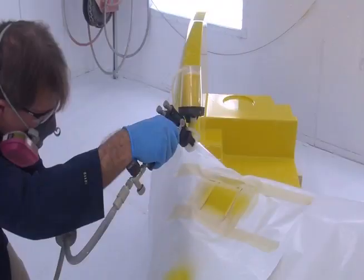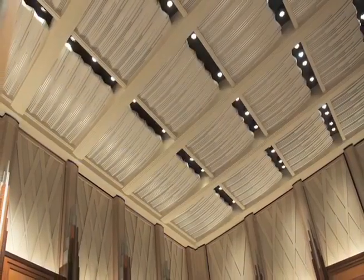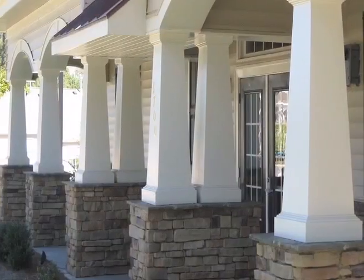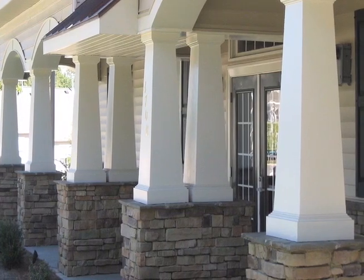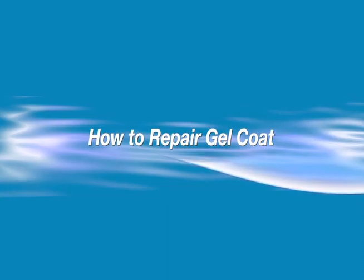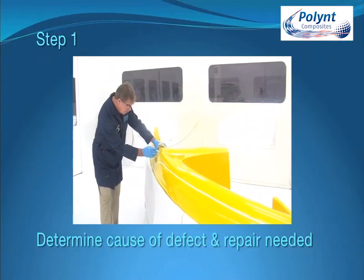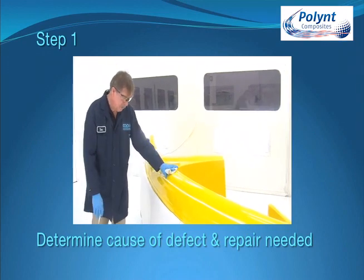In this video, we'll show you how to repair some common gel coat defects to produce cosmetically appealing FRP composites. The steps for repairing gel coat defects requiring gel coat application are: Step 1. Determine the cause of the defect, also determine the type and extent of the repair needed.